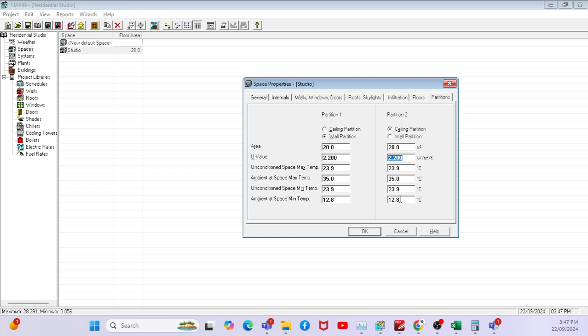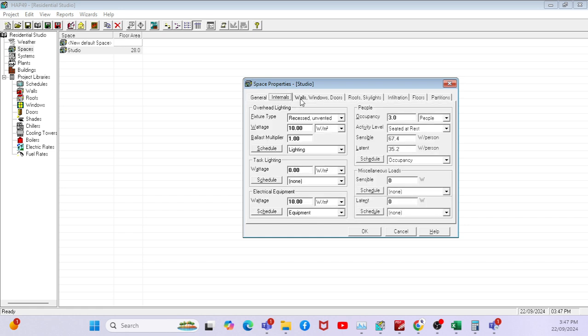Is everyone clear? Any doubts? No, sir. Sir, one doubt here. The ceiling height you mentioned, is it the soffit level or the false ceiling? No, it will be the clear height, the full height, because even if you take return, that return will go above the space, above the false ceiling. So you still have heat. That means you have to calculate for the entire space. Clear, right?